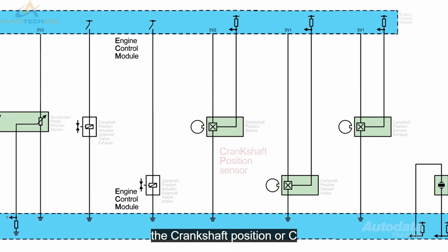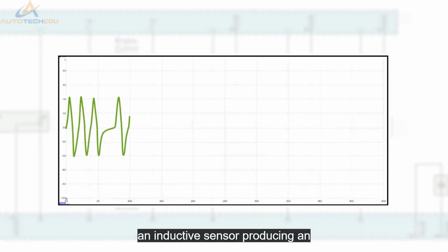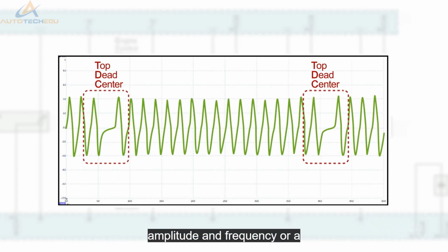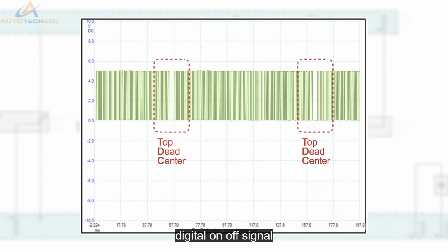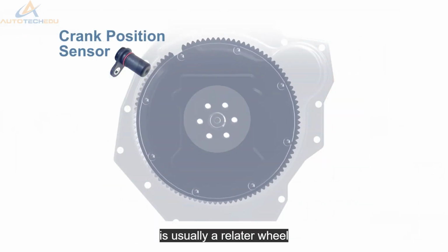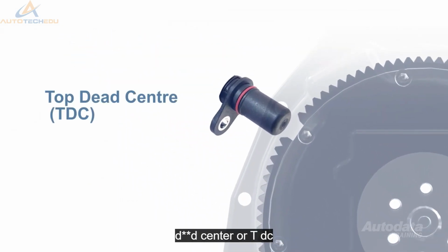The crankshaft position, or CKP sensor, can be an inductive sensor producing an AC waveform of different amplitude and frequency, or a Hall effect sensor creating a digital on-off signal of varying frequency. There is usually a reluctor wheel reference gap to identify top dead centre, or TDC.